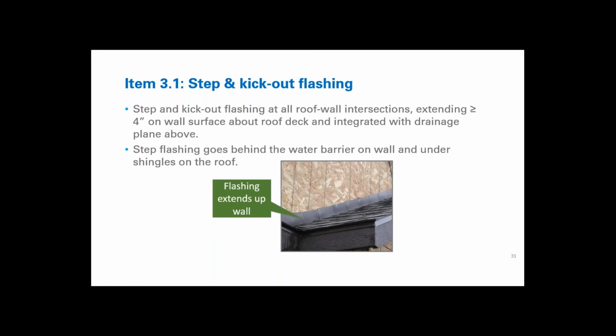Again, this intersection is a weak spot for the exterior drainage system. And it's important to lap the drainage plane from the wall on top of the step flashing and to lap the shingles on top of the flashing. So basically what we're saying is just make sure you think about how the water's flowing here and don't tuck your raincoat into your underwear, is kind of the Joe Stiebrickism on this one.